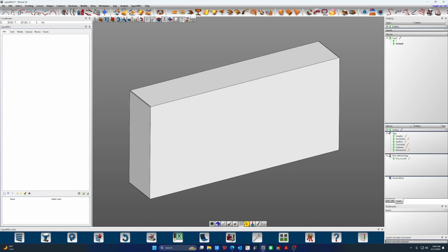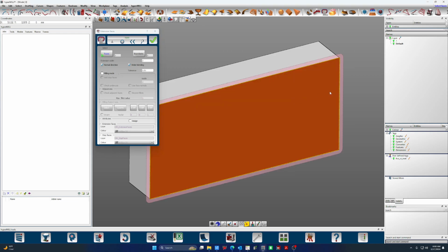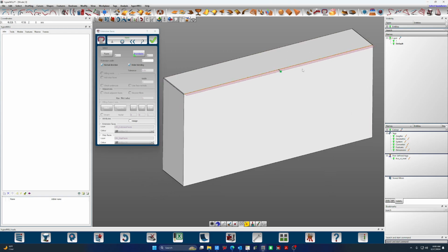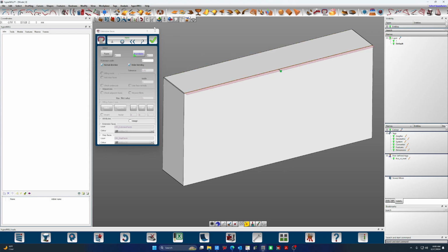I mentioned earlier that when we have trimmed faces that are bound, we want to extend them. If we don't use the untrim function and the extend face function, we can use this tool, extension faces. Now this is something a little newer in the last couple years, and this is an awesome tool, frankly, where we can select a face and have it give us extension surfaces around that face or just specific boundaries. Now, that was a perfect example of contextually, I had my mouse here in this area, I drove it towards the edges. If we reset, if I did that same thing and click here, it's actually extending it tangent, coplanar to this top face because that's where my mouse came from.